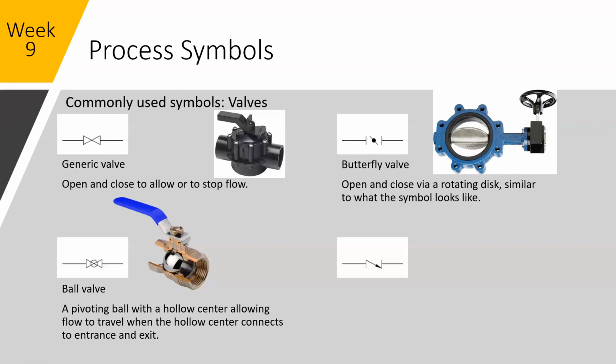I see these used a lot to throttle flow under high pressure. These seals tend to leak a little, so some applications may not work for this. If you have an application that might have a lot of debris in the water, it could jam a butterfly valve, so it might not be the best design decision, but that's what one looks like.